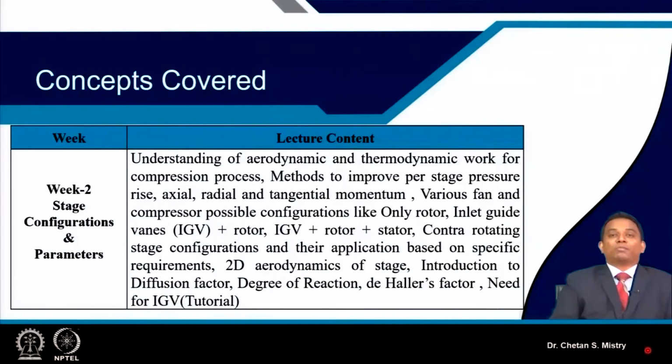In order to estimate the diffusion per stage, or for all your stages during your calculation, you need to calculate the diffusion factor. This diffusion factor also helps us count the number of blades. How many blades you will be using can also be estimated if you assume your diffusion factor to be some number. And we have seen that number, as per the recommendation, is a maximum of 0.5.